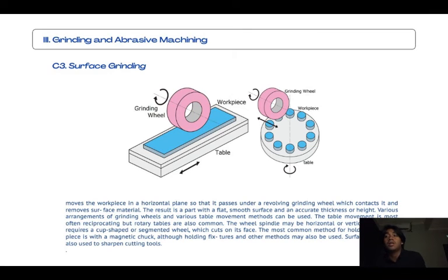The grinding wheel is soft and made with a very open, porous structure to provide space for flow of cutting fluid. Now the wheel spindle is lowered gradually as the wheel wears. Continuous cross dressing is normally used, and wheels can be dressed with a form if desired. Now the cutting forces are high, and the machine must be rigid and capable of closely controlled table speeds, otherwise wheel breakage could occur.